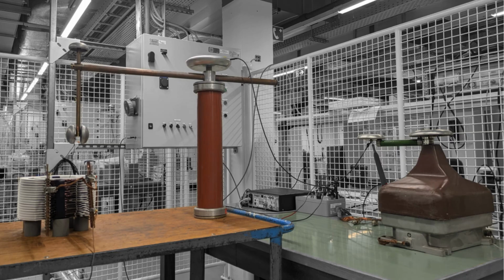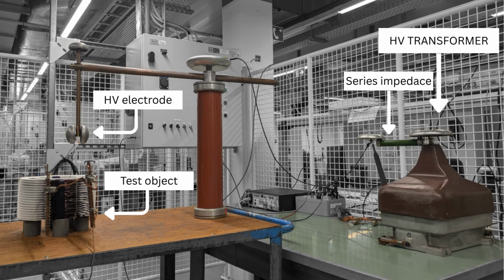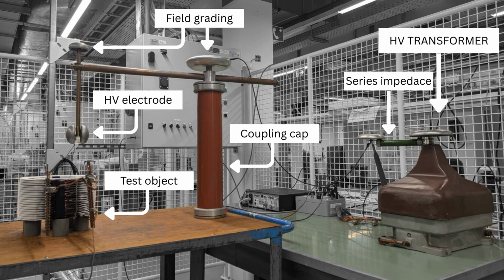And here we can see we set up our test coil in the circuit. The voltage is supplied through this high voltage transformer, through the series impedance and into the test object via this high voltage electrode. The coupling capacitor is then here, and those bushings are added to prevent external PDs being caused by sharp corners in the setup.